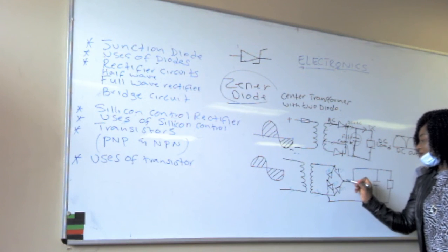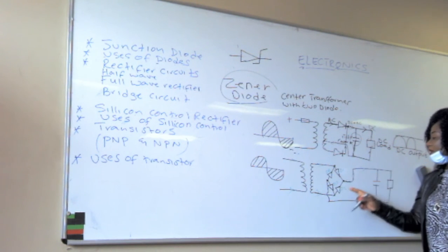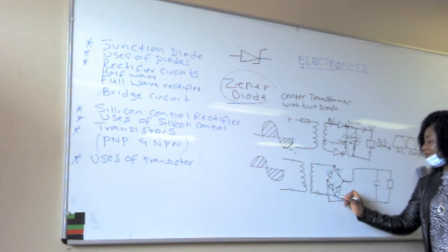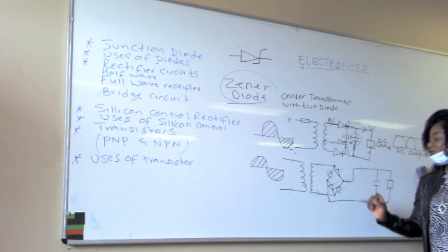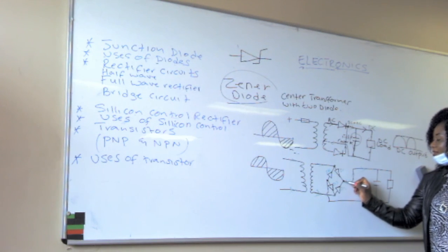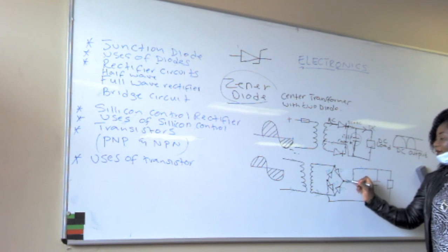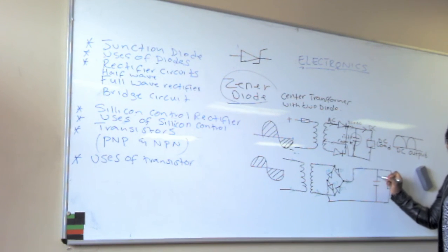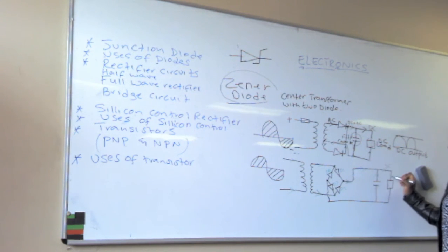So this one comes and brings it out here, fine. Then the bottom current here, the negative current, when it reaches this junction, between D3 and D2, which one is conducting? D2. D2 will conduct, and then they will reunite here. And then we have a strong AC plus DC here. Then the AC will be filtered out into the capacitor. DC will come out here to the DC load. And then we have this result.